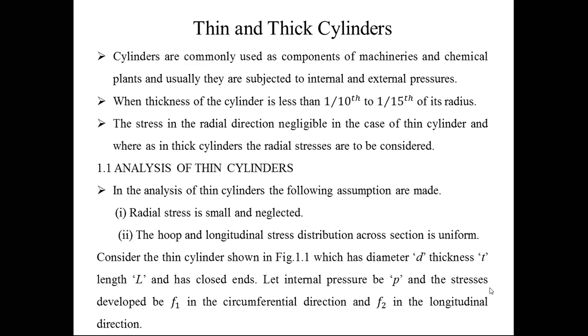What is radial stress? It will be shown in the figures. The stress in the radial direction is negligible in thin cylinders. Actually, the stress in the radial direction is there, but in the analysis we neglect that stress, and also stress is considered uniform. Using these two assumptions, we can analyze the thin cylinders. In the analysis of thin cylinders, radial stress is small or negligible.